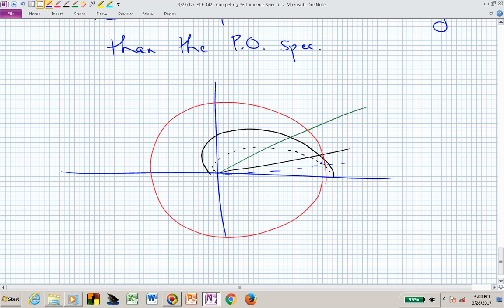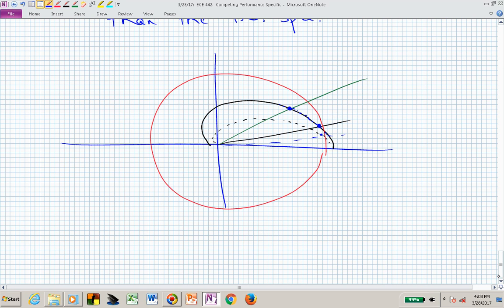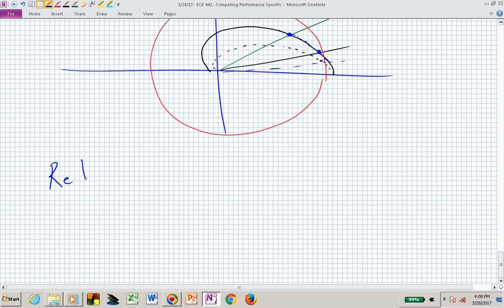What I'm hoping that you start to see is that if we moved along this constant zeta curve, then as we move along and increase the angle, we actually are shortening, or making our radius smaller between this point and that point. And making our radius smaller produces less settling time, which is usually in the direction that we are allowed to go. So one way to approach this problem would be to reduce the radius.